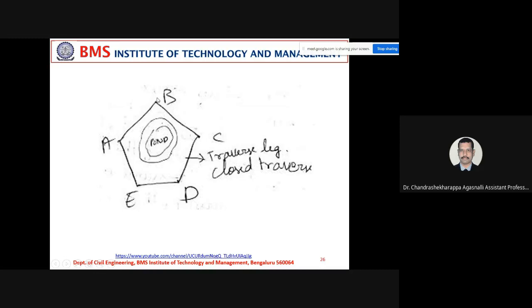Then from here you can look at this point C. From here, this will be your north. Whether you can take the whole circle bearing, yes, north. This is almost 90 here, okay, north 90 degree. Or if it is more than 90, say north 100 degree, this is a whole circle bearing.